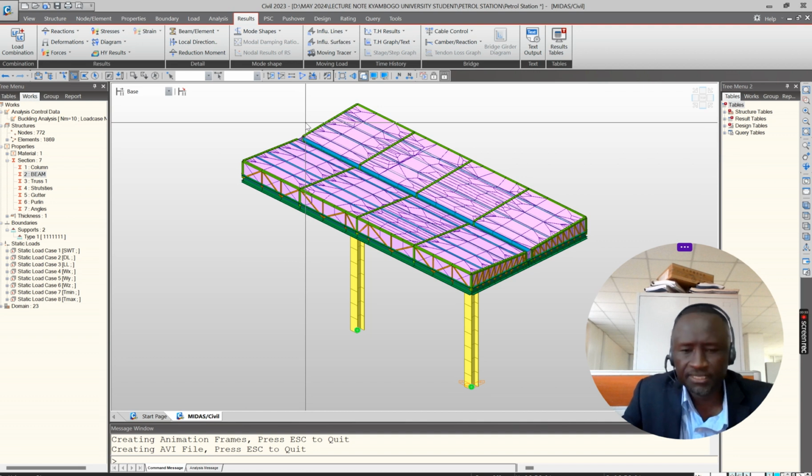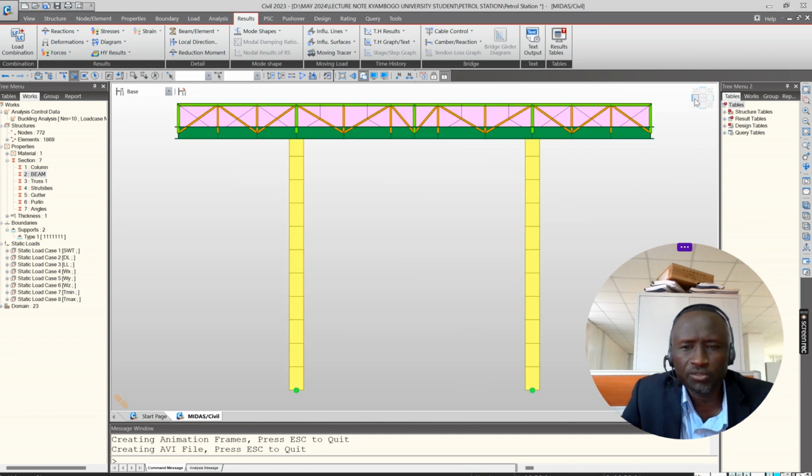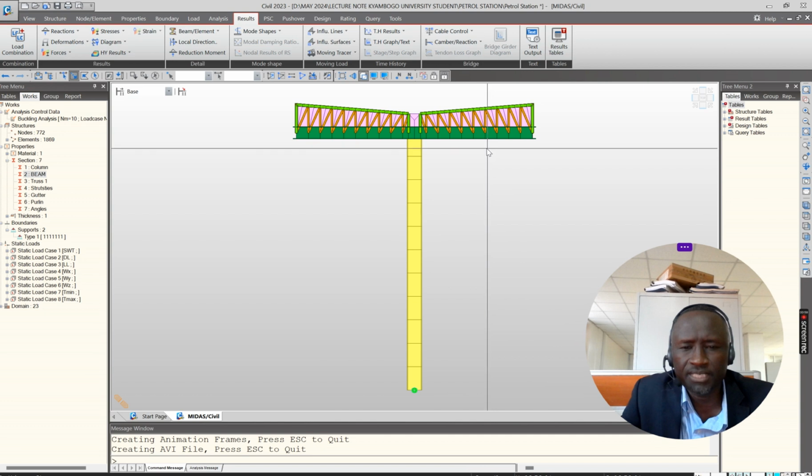One, canopy structures are subject to wind effect, both horizontal, vertical, and sideways. So you have to be very, very careful, especially with uplift effect. It's worst with canopy with only two columns, or columns which are centered like this. This is more or less an unstable construction.